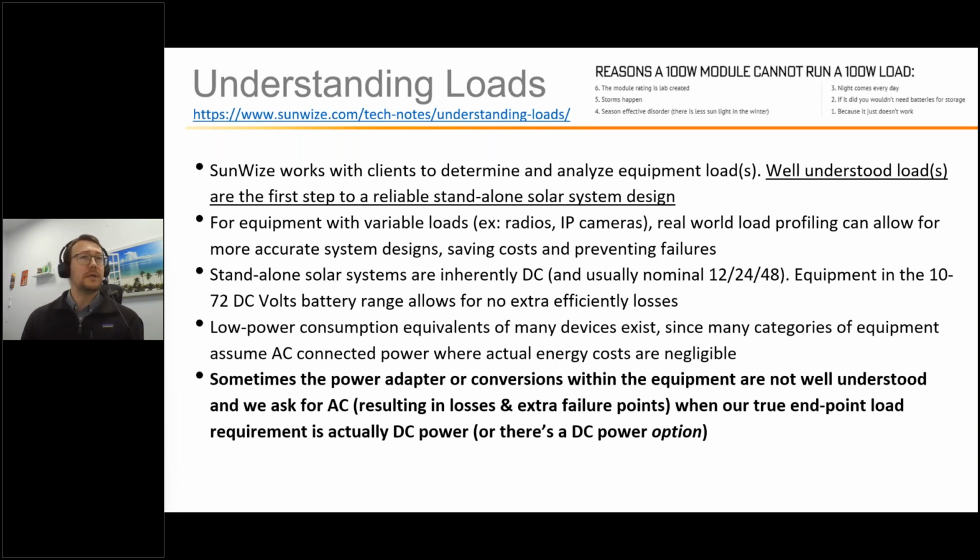When you think you need AC, maybe stop and ask one more time: is the end device really still needing AC, or is it possible that we could provide a DC option or bypass that inverter entirely? These are the sort of things that we'll be asking when you work with us, to make sure that we're not losing opportunities to have a more efficient design.